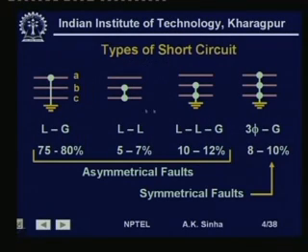So, to analyze faults which are asymmetrical, we need to work on a three phase basis. That is, in case of symmetrical faults, we used a single phase basis of analysis because all the three phases were identical. If you come to know the current and voltages in one phase, you can always find out the currents and voltages in the other phases because they will be of equal magnitude and displaced from this phase current and voltage by 120 degrees.